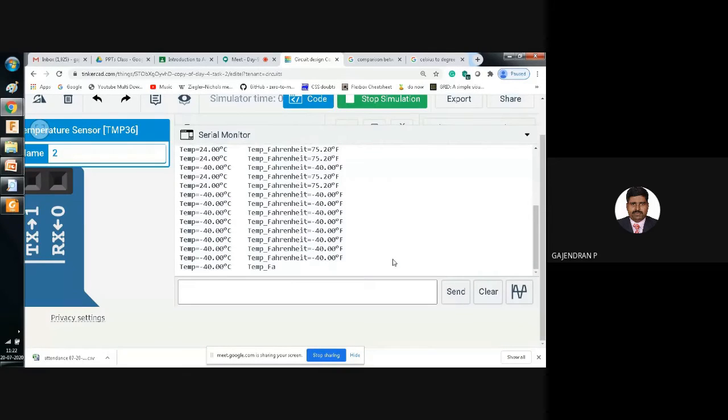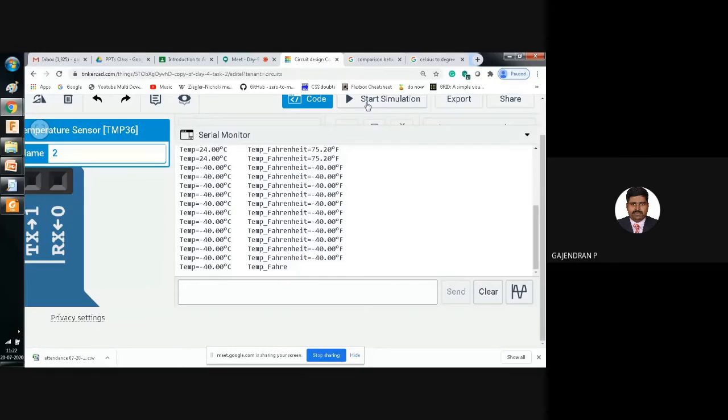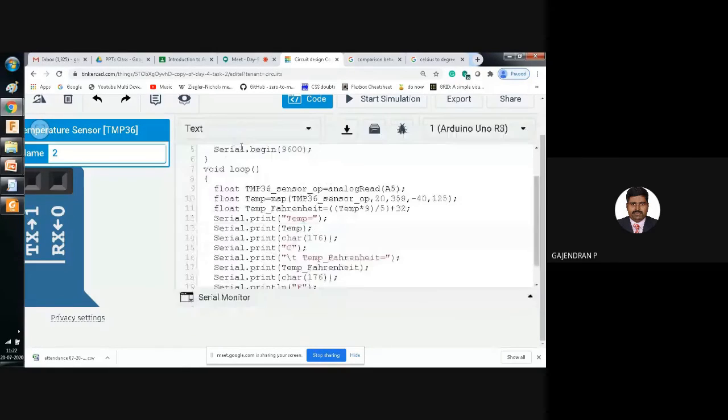Two new things we have learned today. One is how to read the analog output value, then accordingly how to map it. So these are all the ranges. It is no longer 0 and 1023 all the time. According to our practical input, this is the minimum value of the analog read I am going to receive, and this is the maximum value I need to read. And I am going to map it with the required from value and required output value. This is the one thing.